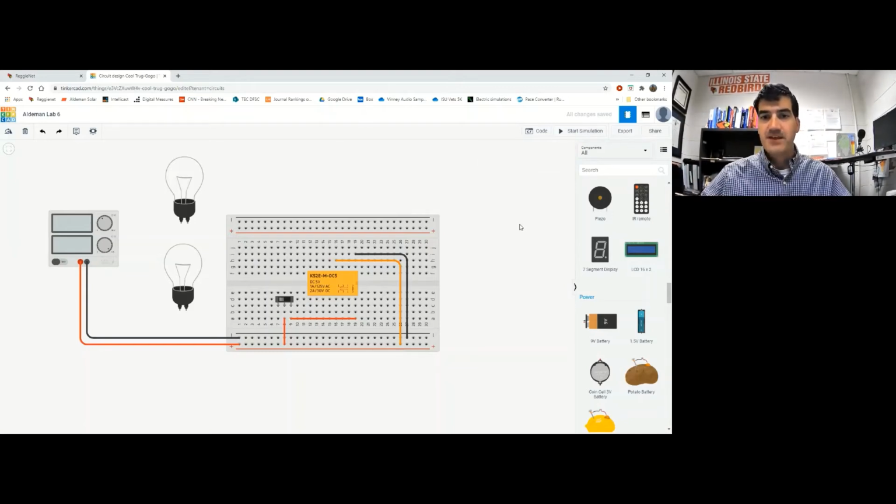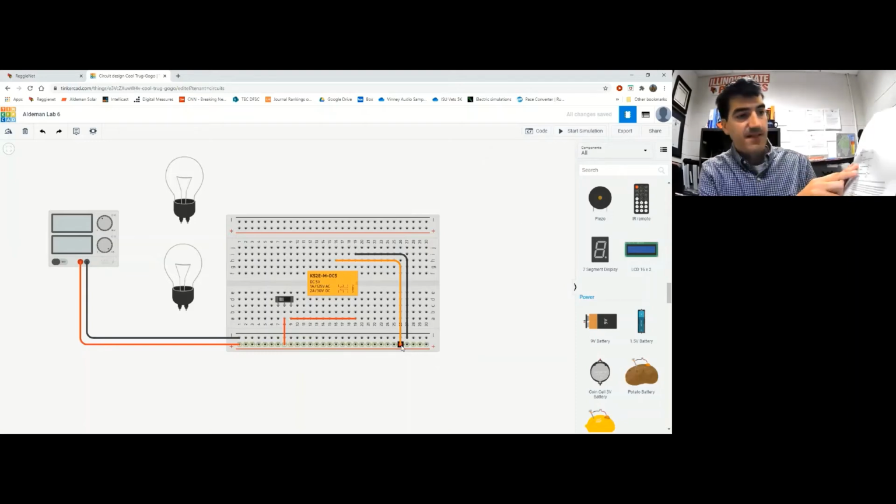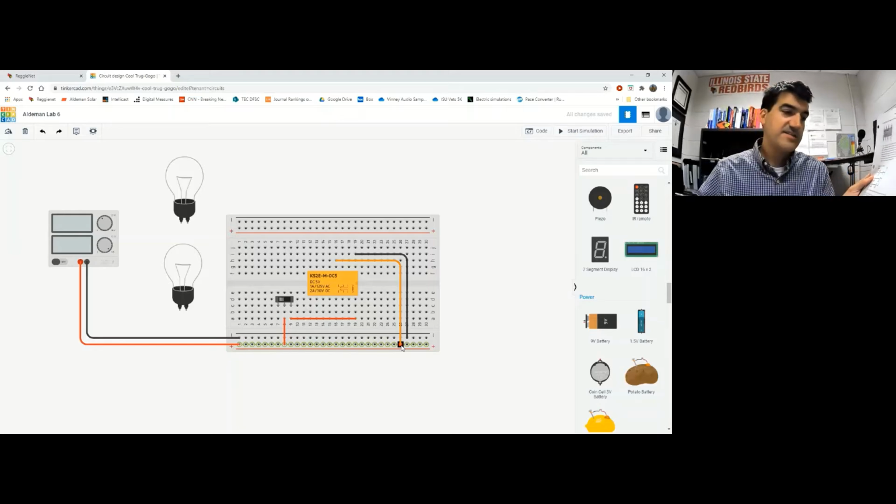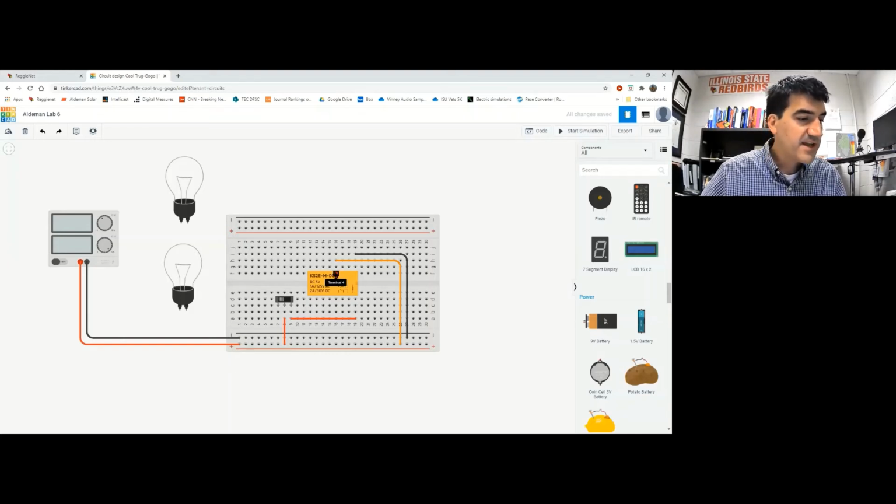Okay. And so now I've got this wire right here from 24 volts to the common of what's going to be CR1A. So CR1A is a normally open contact associated with this pin right here. It's going to be associated with this common. And so the pin I need to use is the normally open contact associated with pin 4. So which one is that? That is 8. Right. You can see that little diagram right here too. It's smaller, but it's there. So the normally open associated with terminal 4 is pin 8.